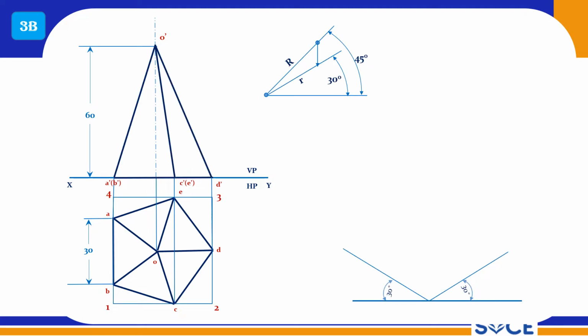So once you get the simple front view and top view, draw the iso scale and start projecting. So measure each, right, convert every given dimension to iso value, use that here, right. So for example 1 to 2, measure here and convert here, that should be used here, right. So similarly you have to convert all the dimensions, right.